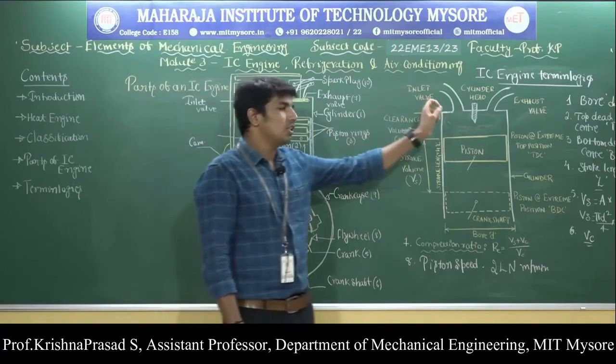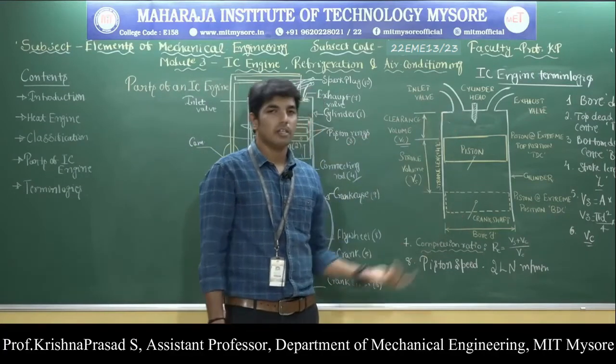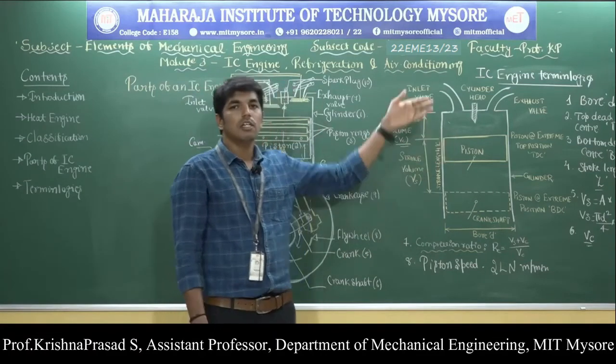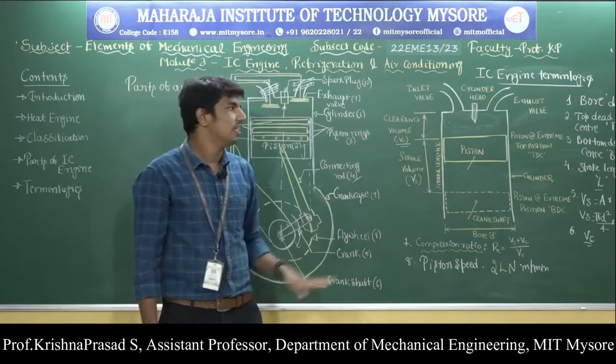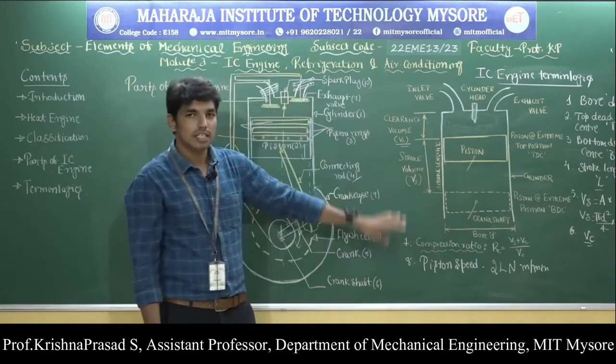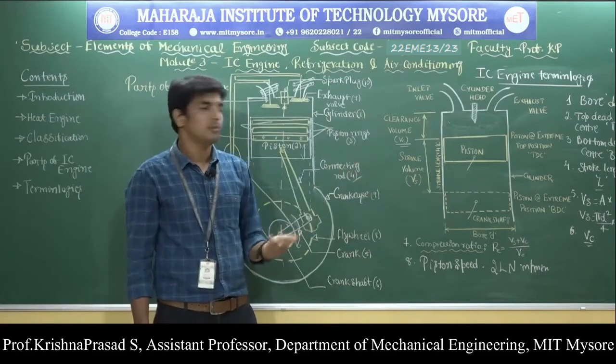I repeat. What is meant by the bore? The bore is the inner diameter of the engine cylinder. Top dead center is the extreme position of the piston near the cylinder head, abbreviated as TDC. Then bottom dead center is the extreme position of the piston near the crankshaft end, abbreviated as BDC.